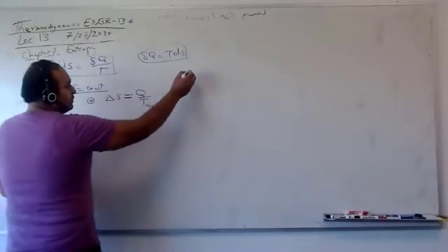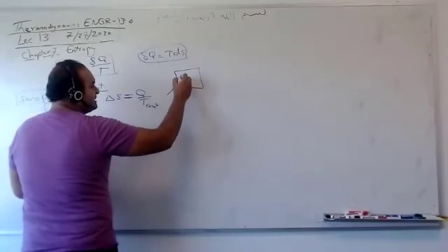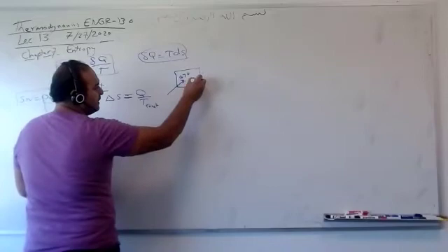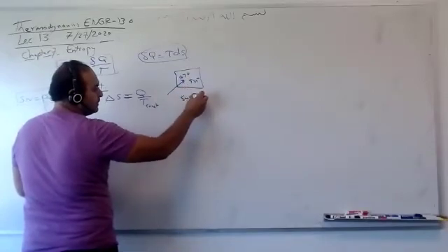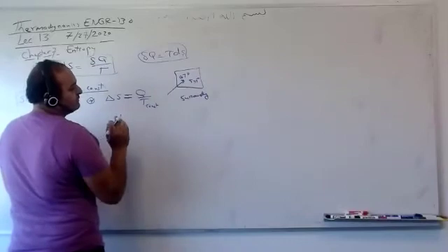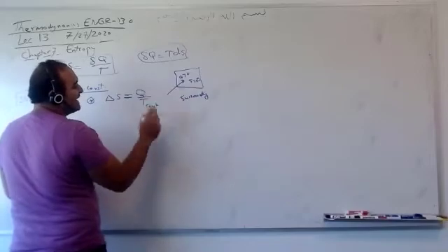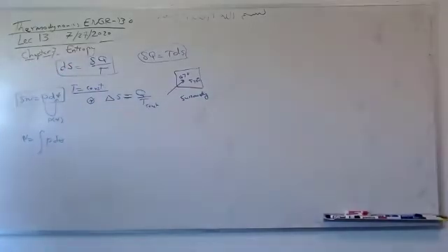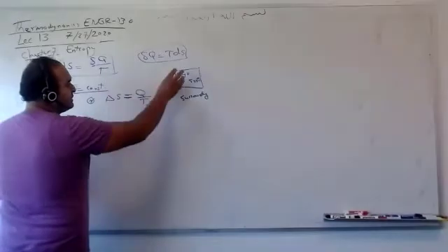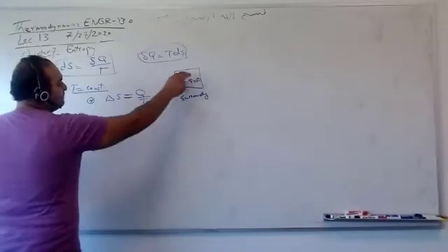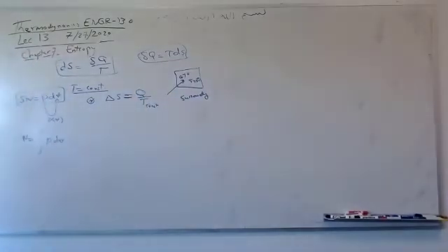For the heat addition or rejection, let's say you have a system and a surrounding. If you add heat, this Q is positive for the system, but negative for the surrounding. This Q with respect to the system is positive because heat is added to the system. But this Q with respect to the surrounding is negative. That's why delta S equals Q over T is negative for the surrounding. And if the temperature of the system is also constant, the equation works the same way: Q positive, negative for the system; for the surrounding, negative, positive. This is what we took last time.